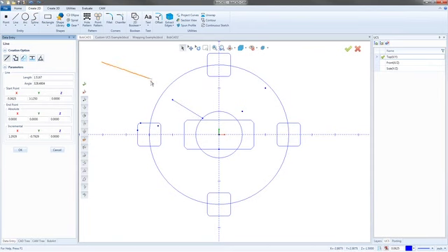And then what's cool about the lines, and this has been around for a few years now, but I think a lot of people can always use a refresher on it. When you click on the line, you'll notice the difference in color between this line and this line. This line, I can still modify. This darker one's still modifiable. So I can come in and say, okay, the length is 2.5. Ooh, not 25, 2.5. And the angle, I want it to be a clean 290 degrees.